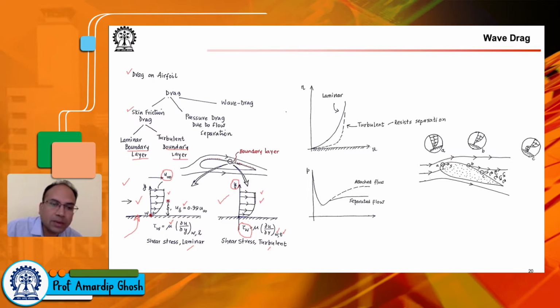We will see that depending on Reynolds number, Mach number, etc., and also many other conditions determine whether this boundary layer is going to be thick or thin, whether the boundary layer will affect the inviscid flow field outside in a very strong manner or in a weak manner, whether that interaction with the inviscid layer will feed back into the boundary layer and couple with it. Those things we will discuss, not in an introductory course, but perhaps in an intermediate course. At this point, the idea is to give you a flavor of all these various things that happen in aerodynamics.